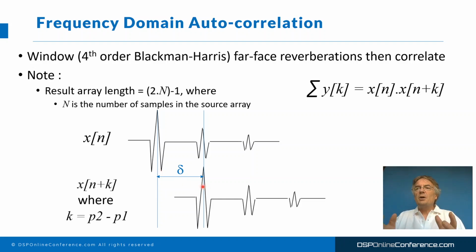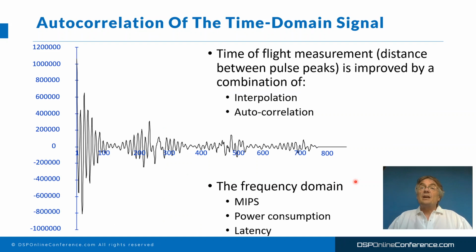So we send out a pulse, we get reflections and so on. By measuring the distance, the delta time domain between the primary pulse transmitted and received, we get the time of flight, and from there we can detect the structure of the material. Here's a diagram with a sort of summary of the main benefits.